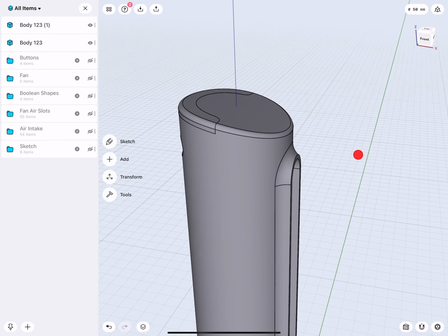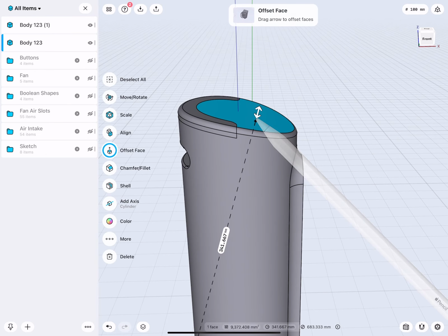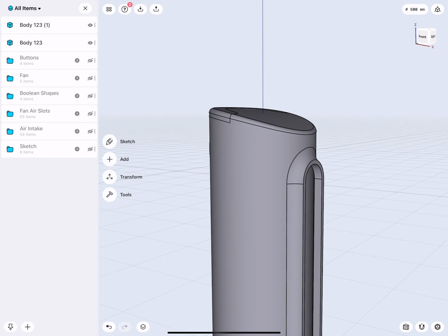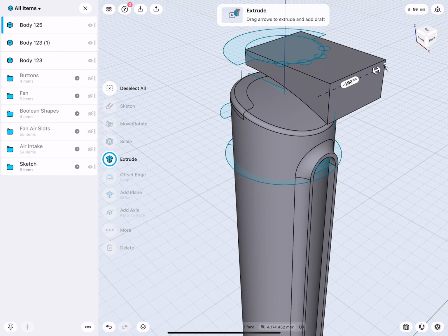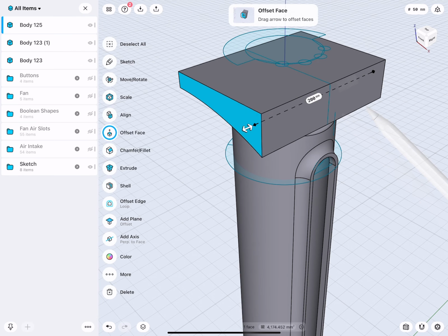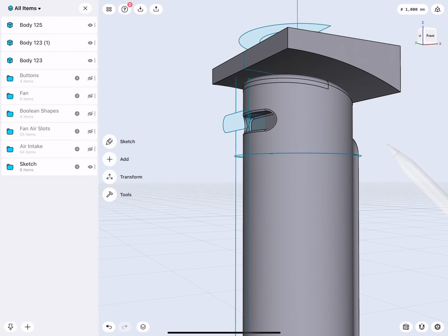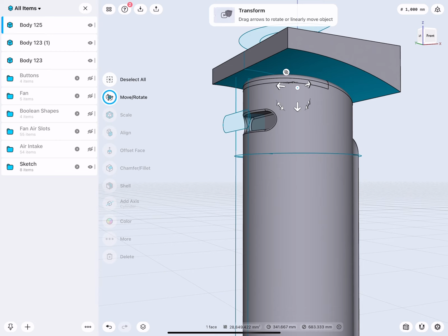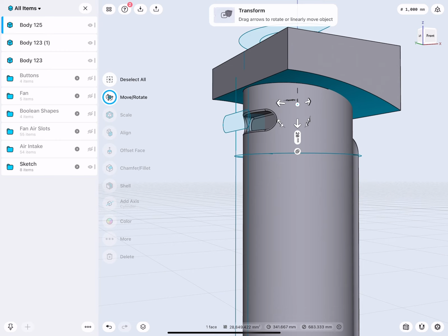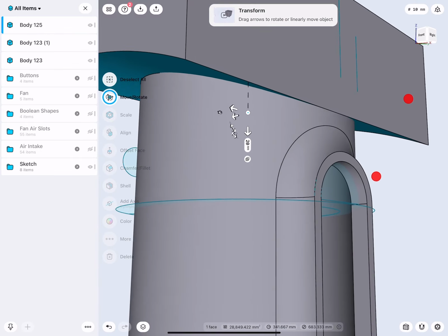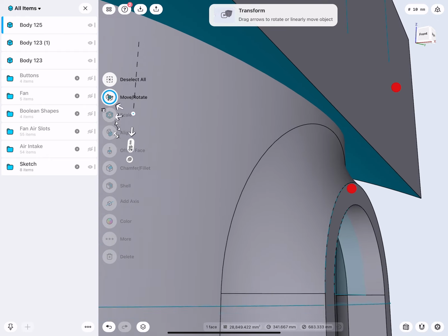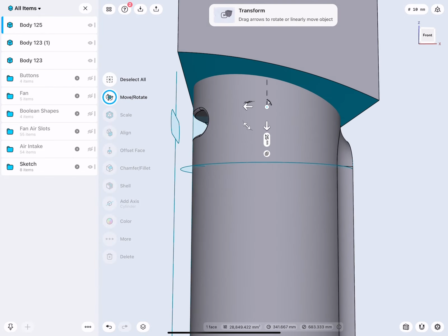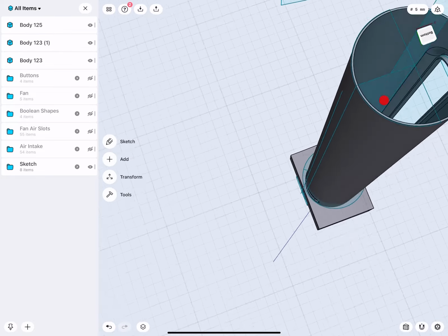And now what we would like to do is we want the top part to separate. And then we want to create the lip and groove. Let's turn on this sketch and we will extrude this 100, 200. There we are. And same steps again. This will go down till there. So this is 20. And then I can pay attention to when I move this down 25. Yeah, it does not intersect there with the fillet. There it is. Good. Very nice. Okay. Beautiful.